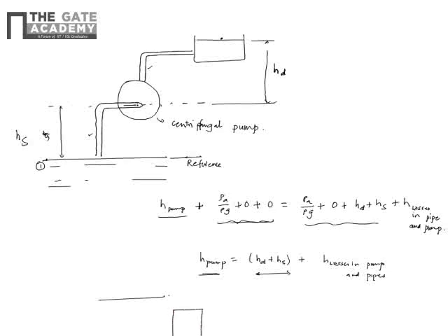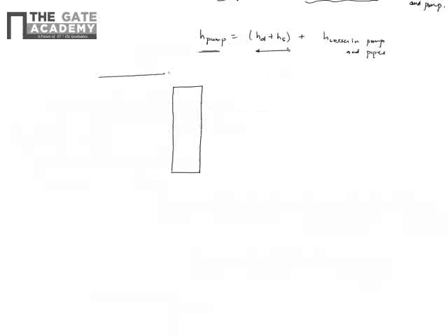Like if you have a shaft, let's say the shaft is connected to the impeller and the shaft is supplying power P. So this is your shaft output. The shaft is connected to the impeller, but in between you may have some mechanical losses because of the friction at the bearing and stuff like that. So that is all mechanical losses. And what we get at the impeller is the power minus these mechanical losses.